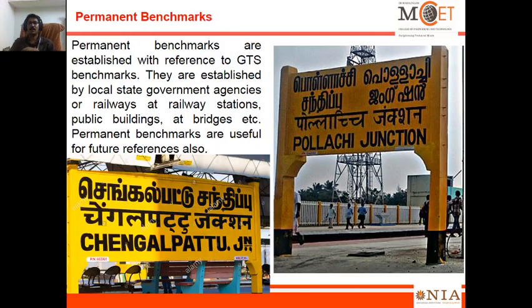Next comes the permanent benchmark. These are established from the GTS benchmark. They are established by local state government agencies, or railways, at railway stations, public buildings, bridges, etc. The permanent benchmarks are useful for future reference.